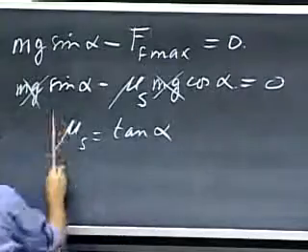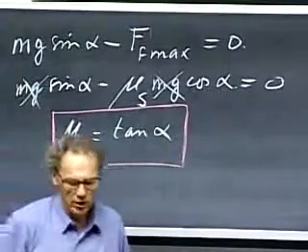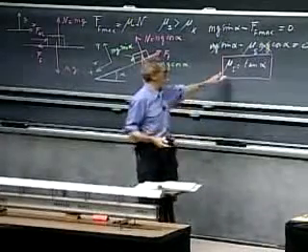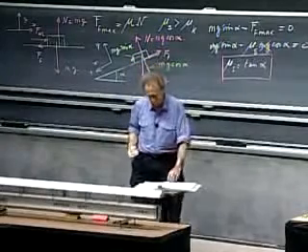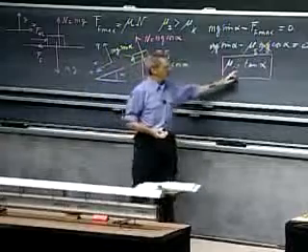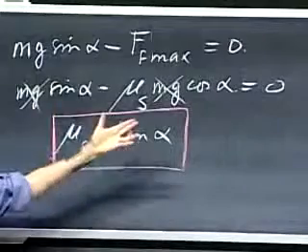It's that easy to measure. So you increase the tilt. We will do that later until it starts to slip, and then at that critical angle that it starts to slip, you have a value for mu of s, for the static friction coefficient. It is very non-intuitive that this friction coefficient is completely independent of the mass. The mass has disappeared.